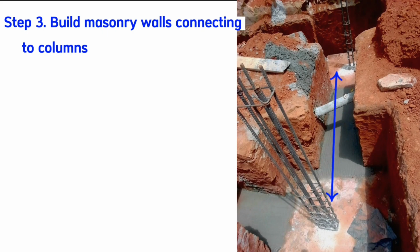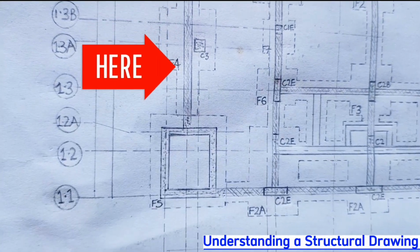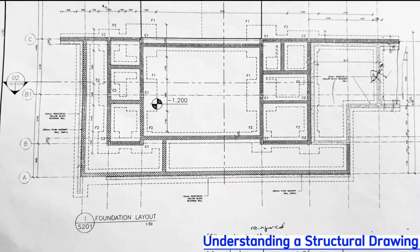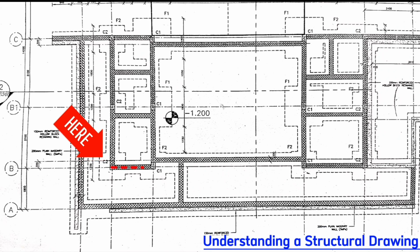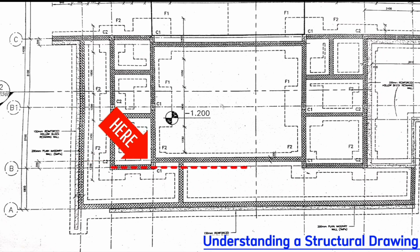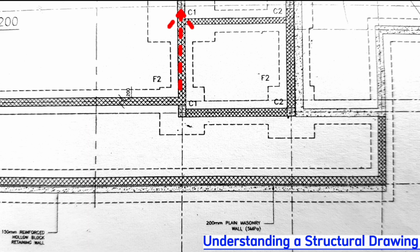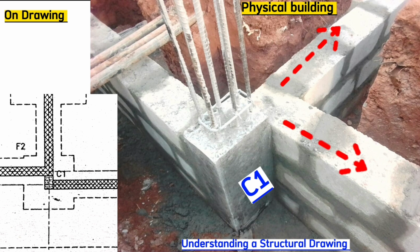To build the walls, we follow the foundation layout. This is the symbol for the load-bearing masonry block work. So these are bricks or blocks running along here like this. Along this grid line B, this wall starts from column C2 here, goes to column C1 and separates from here at this column C1. One wall takes this direction and another takes the other direction. Similarly on ground, this is column C1. One wall will take this direction and another wall will take the other direction. That's how it's always done.